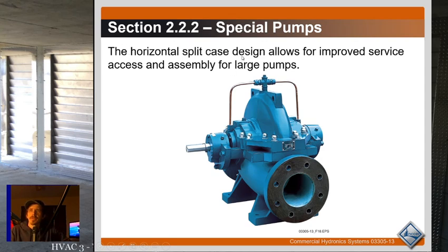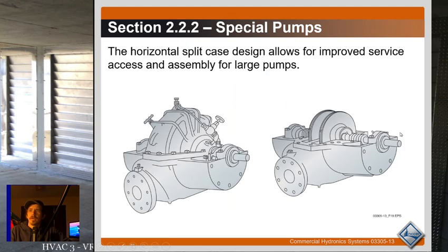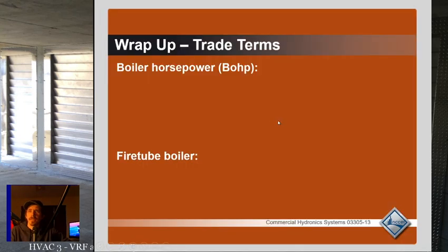Alright, special pumps. Horizontal split case design allows for improved service access and assembly for large pumps. So this would be a large split case pump. So you can see shaft. Looks like a closed suction impeller in the middle there. You can split the case, work on everything, put the case back on top. Hence the name split case.